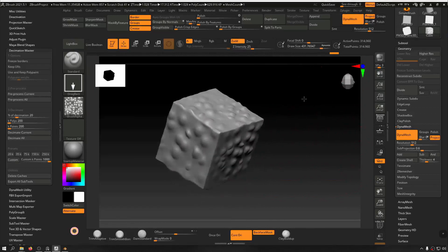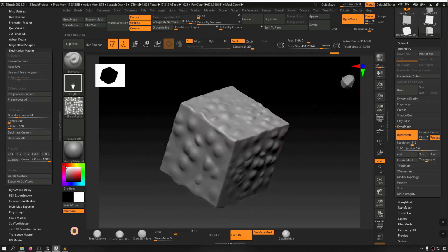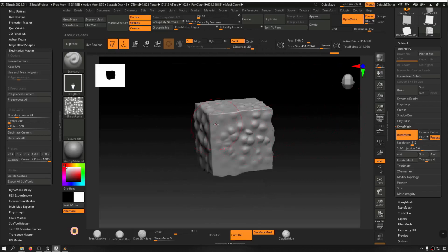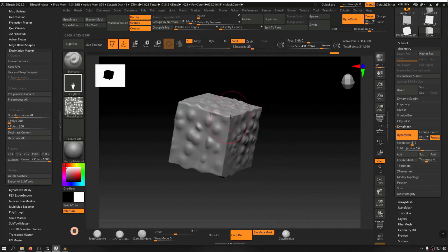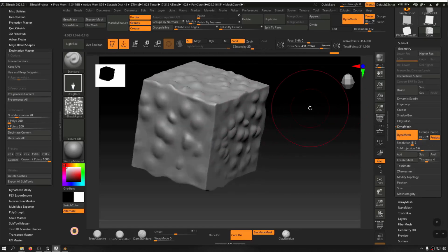And there are times that we are not only exporting these high quality meshes into Unreal, but we are not UVing them as well. It might happen a lot of times that we really do not create UVs and export this directly into Unreal and start texturing there using the vertex color data. Vertex color can store RGB as well. So we are going to use RGB, which stands for red, green, and blue, and assign each vertex a color so that later on we can apply the textures in Unreal Engine using vertexes, not the UVs.